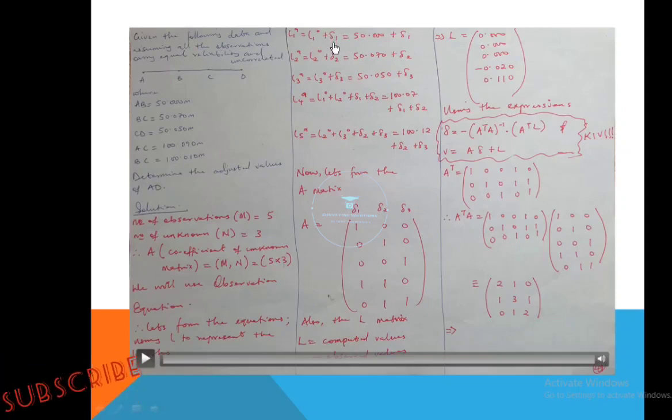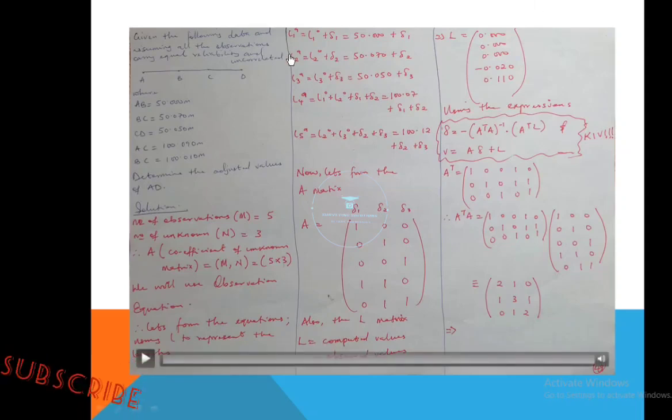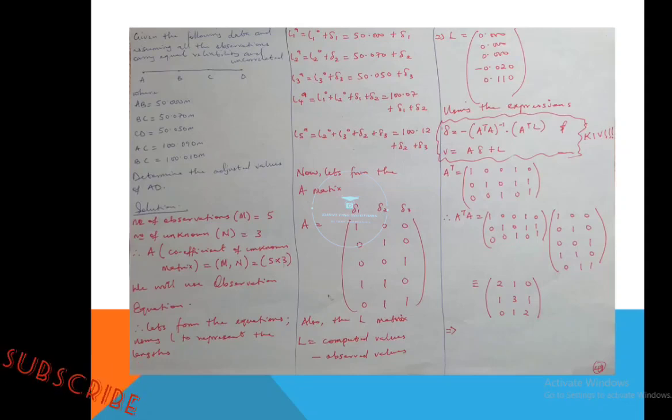We can just conventionally call it the error, because for every adjusted value, the difference between the adjusted value and the observed value is the error we are trying to determine. So now, without encumbering ourselves with so much grammar, this is an expression that we are going to use throughout the course of forming the observation equation. So the first thing, as we said earlier, is that you have the adjusted L1 equal to the observed plus D1.